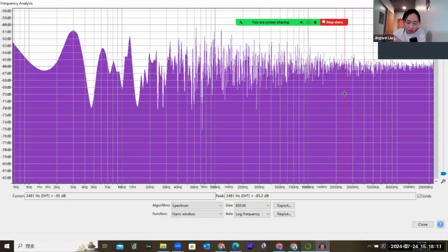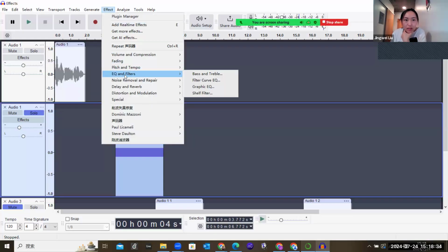So in engineering, this is called whitening. Okay, you whiten some sound to a white noise, which means you have this type of spectrogram, and then you can shape the sound from this stage to anything you want, using filters. So let's try this. Let's see this equivalent filter.